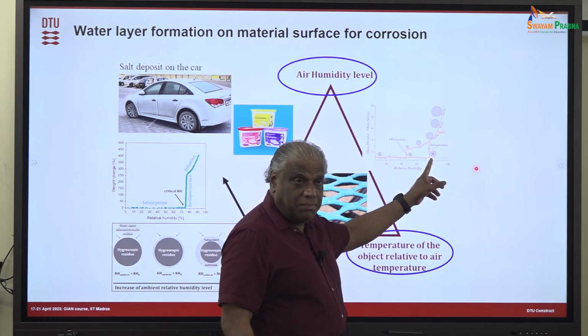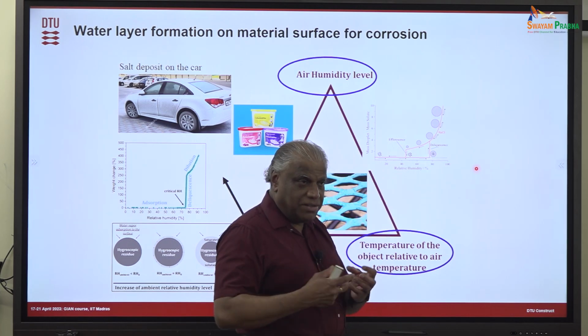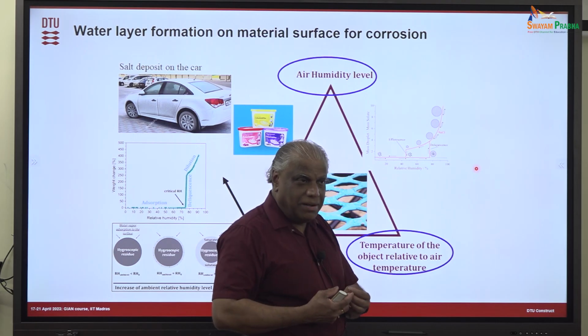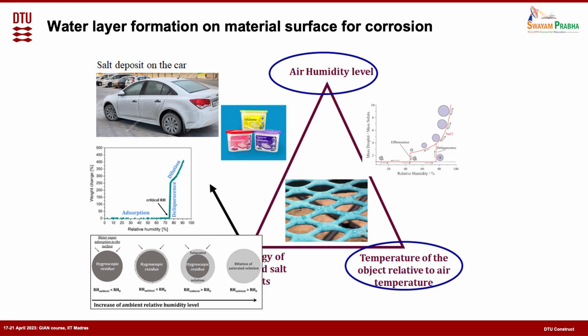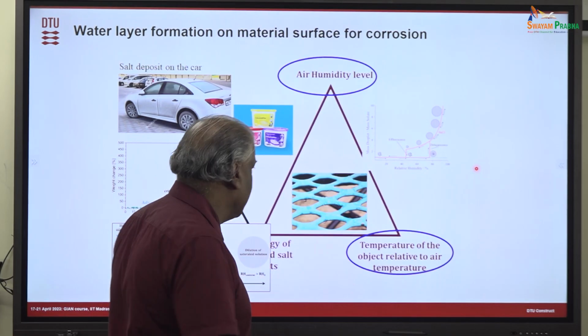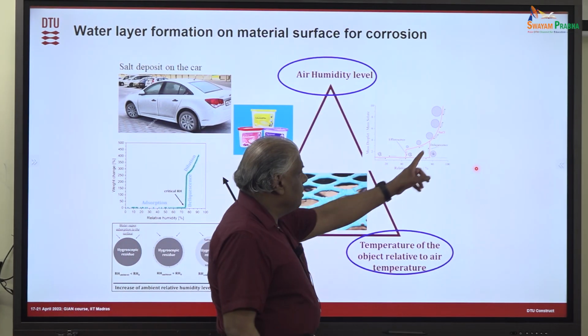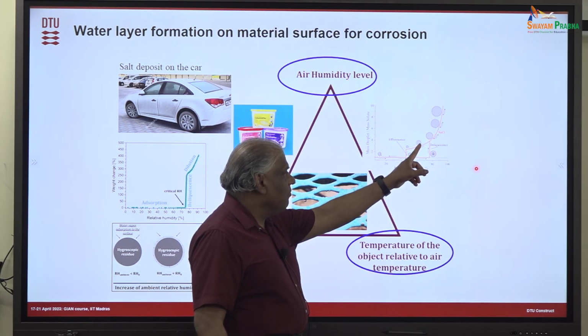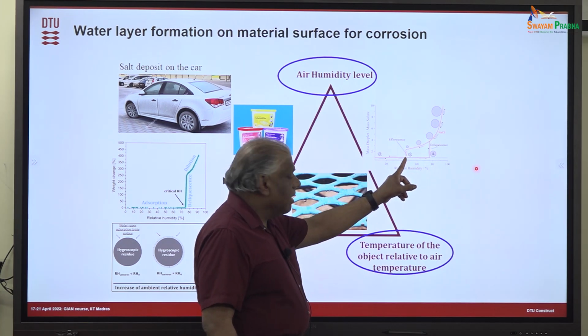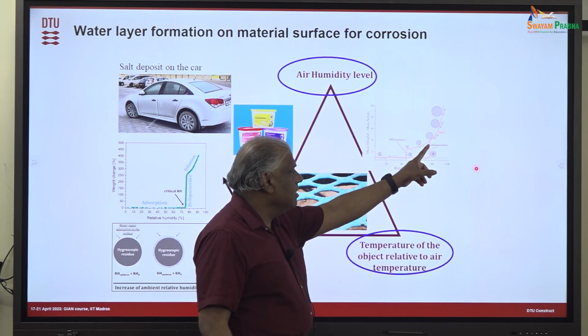It will not happen because of the molecular forces, the way the crystallization has to occur. Like in metallurgy also, you must have learned that when you do the casting, you need to do the undercooling, right? In order to get enough energy for the nucleation and crystallization. Exactly the same thing. It will not crystallize here. Instead of that, you will follow this. It will crystallize at a lower humidity level, with a hysteresis.